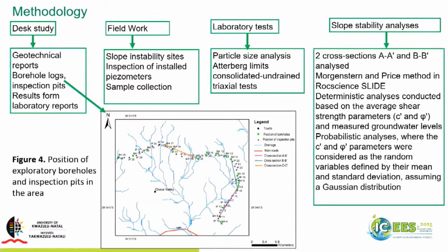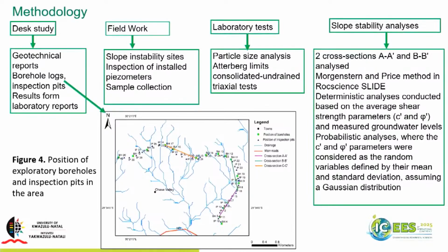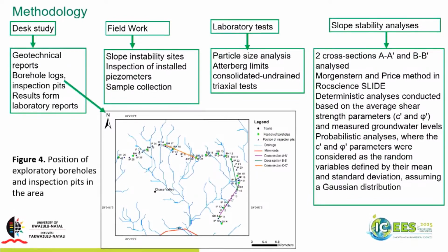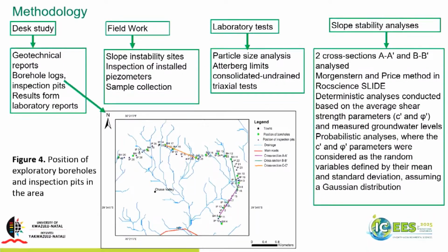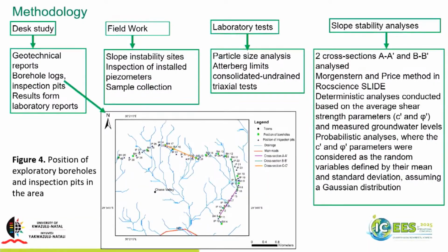So in terms of the methodology we adopted in this study, we undertook a desk study which involved going through geotechnical reports, bore logs, inspection pits, and results from laboratory reports, and this figure 4 shows the position of all the boreholes and inspection pits. And then we did a field walk to instability sites, to sites of slope instability. We inspected installed piezometers, most of which were vandalized, and we took samples for laboratory testing.